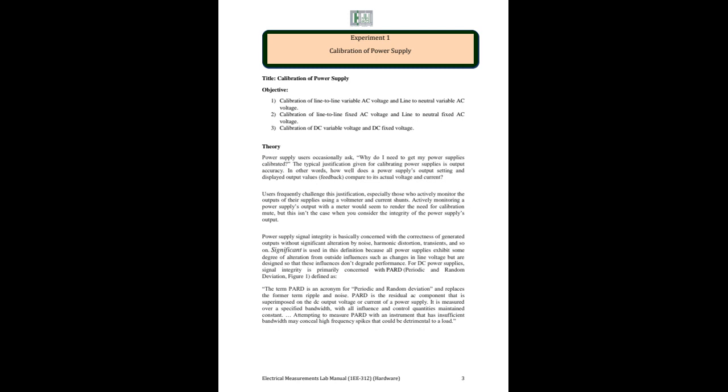Actively monitoring a power supply's output with a meter would seem to render the need for calibration moot, but this is not the case when you consider the integrity of the power supply's output. Suppose we are monitoring the power supply each and every minute, so there is no need to calibrate. But what he is saying is that it is better to calibrate the power supply even though you are monitoring.